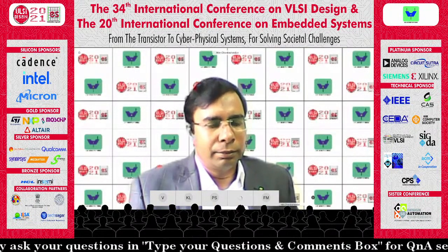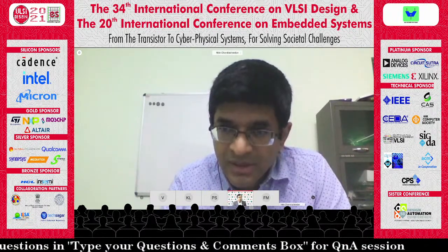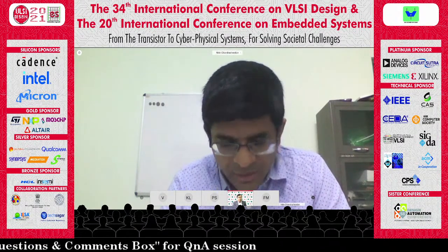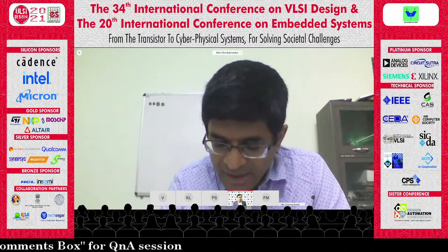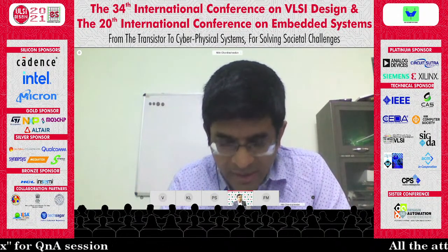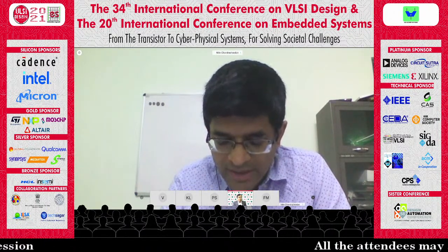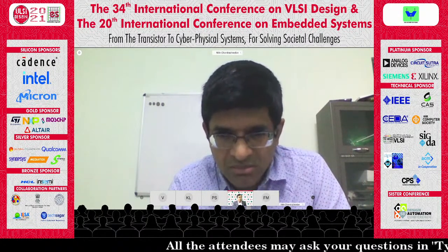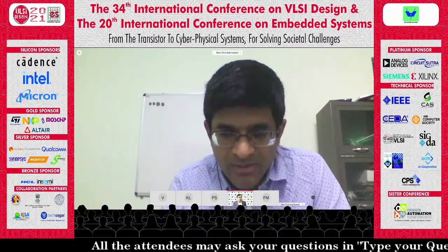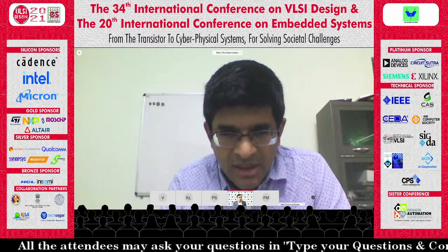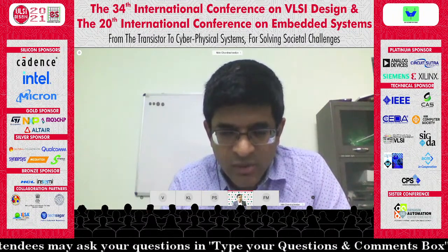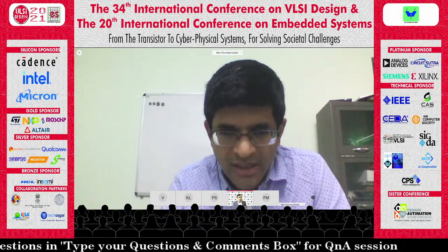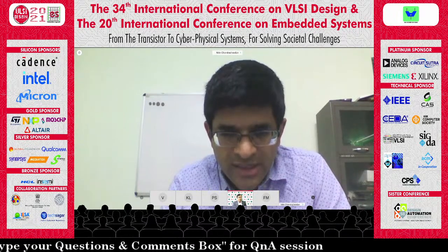So I just had a couple of questions, if I may. Mr. Sharavanan, you are there? Yes, sir. Okay. Primarily with respect to the ASIC implementation, I can see that you have a higher throughput. So that is definitely there. But I was curious why the SCL 180 area was more than 2.5 times, I think, the size of the UMC 180 implementation. Is it because the UMC was more tuned towards a smaller pitch width? Is there any observation on that? Did you try it with any other library, or was it done only with the SCL 180?